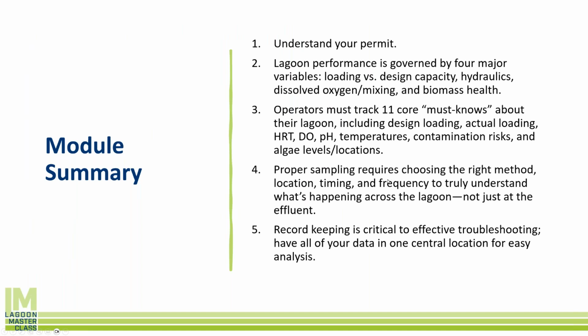Proper sampling. I'm a stickler on this. Proper sampling does not mean just do what your permit says. I'm a huge believer in taking influent samples all the time. Whenever you take an effluent sample, take an influent sample. That way, whenever you have a problem, you have the data already in front of you to make those design or operational decisions.